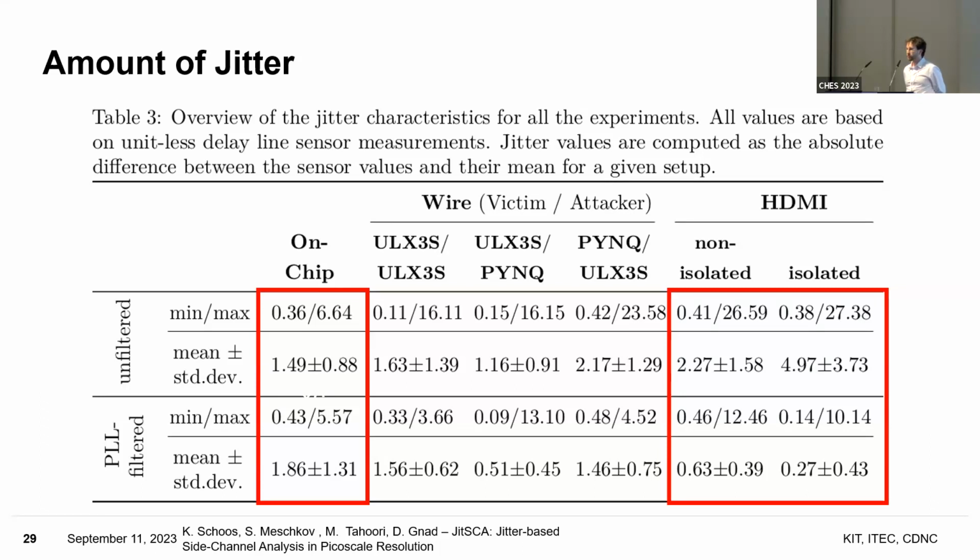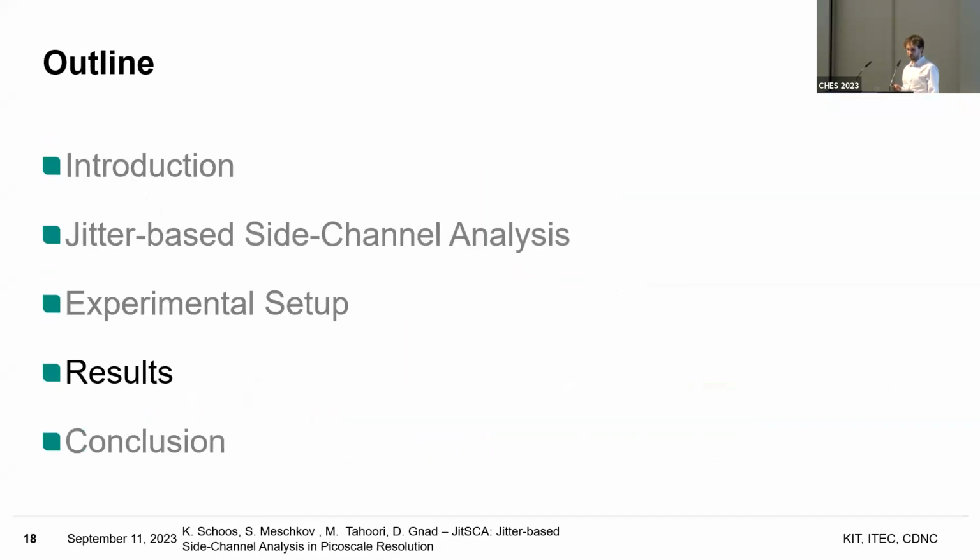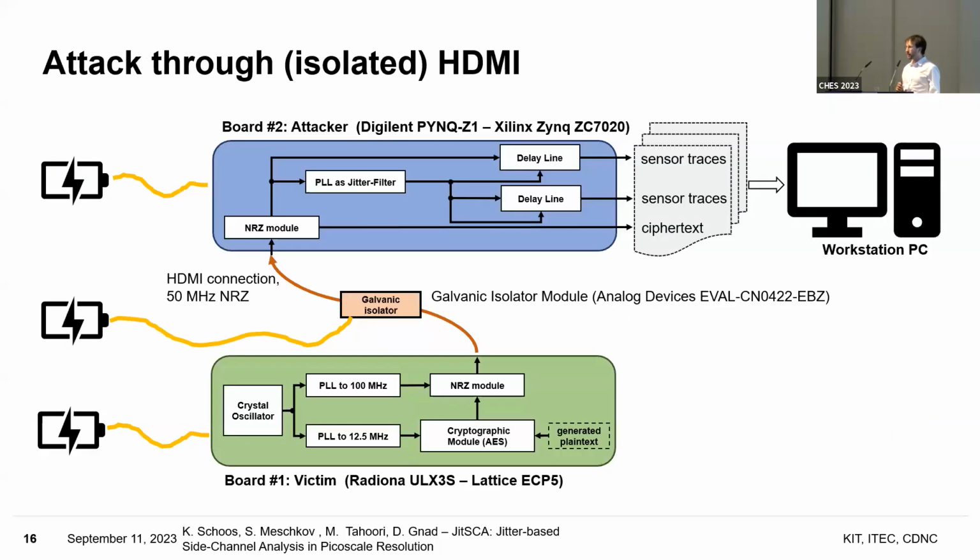We are relatively sure. That's why we did all of these experiments. Like we made these 3 boards. If the input IO would receive more than jitter, it's hard to say where it comes from, but it's only timing because we separated all the power domains. We have a galvanic isolation board in the middle. It's powered. We put power banks to all of these things so that everything is really separated. They are not even plugged into their own wall power supply because we wanted to be extra sure.